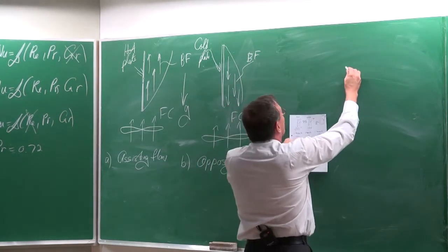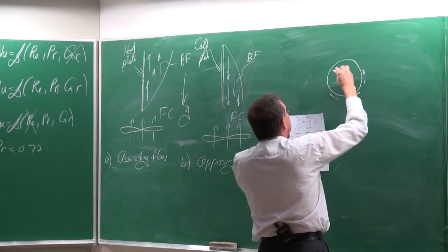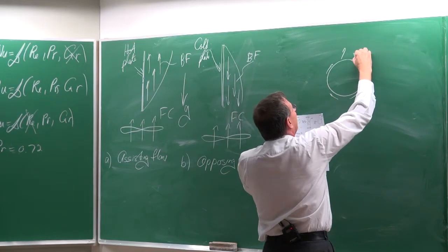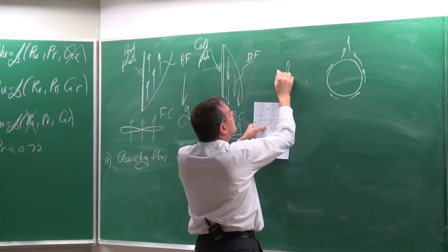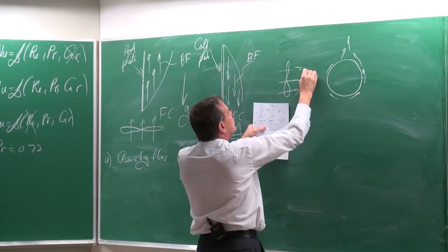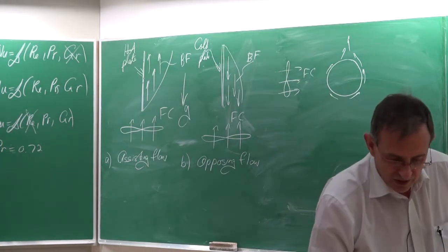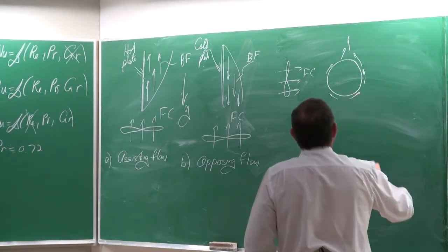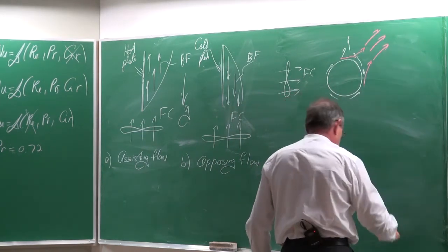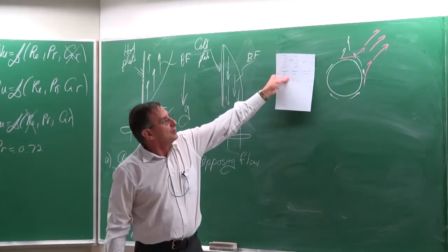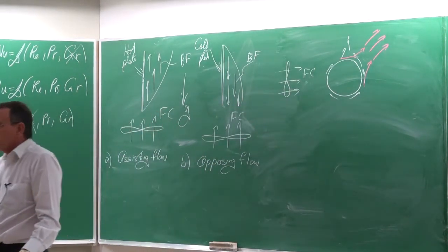And then the third one is the one that I've showed you the sketch of previously, where normally the buoyancy forces would do something like that. Okay, and now we put the fan here. That would be the forced convection, and the resultant streams of flow will now actually move in that direction there like that. So if you just think of this situation without the fan, you will have certain heat transfer coefficients. When you put the fan on, the heat transfer coefficients will increase.